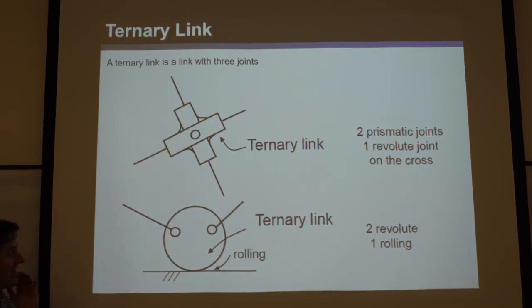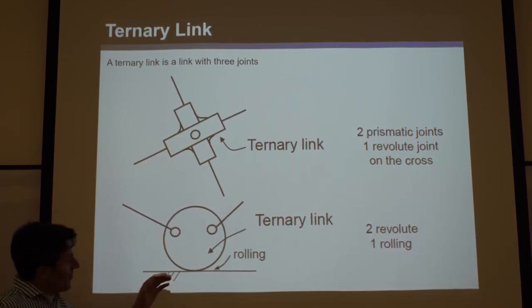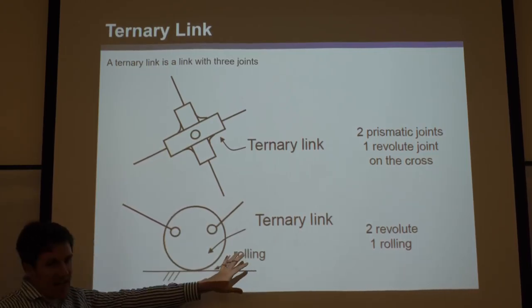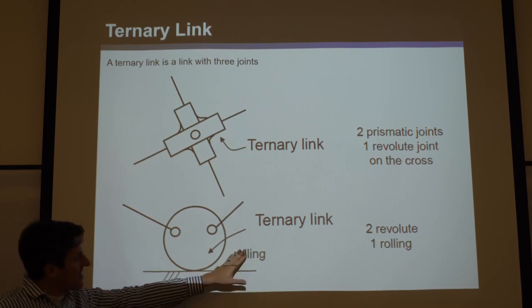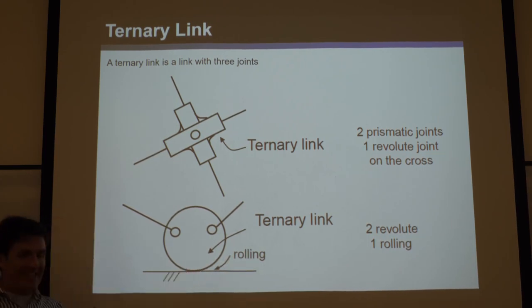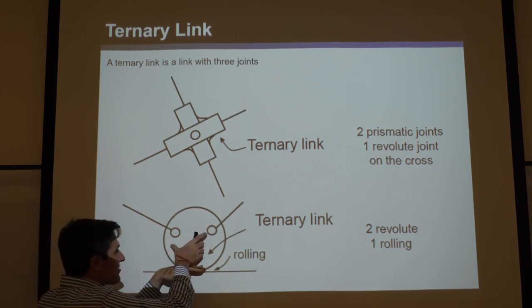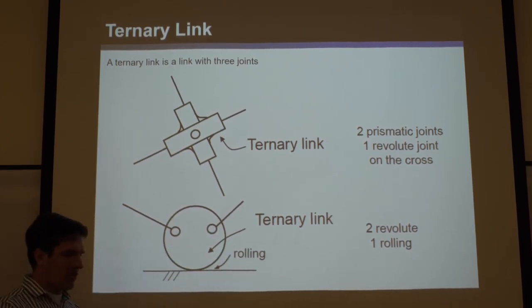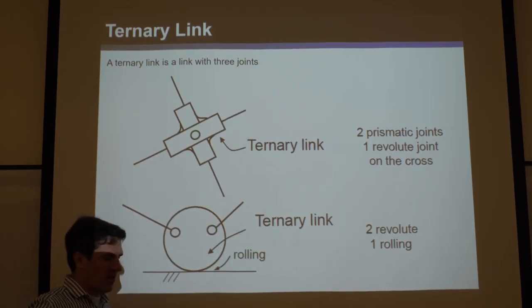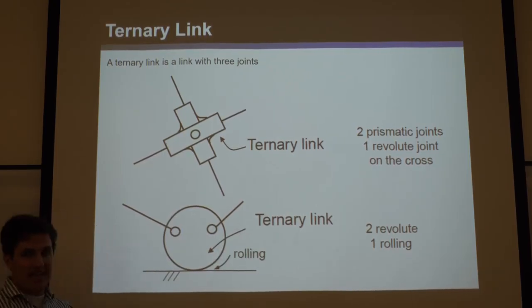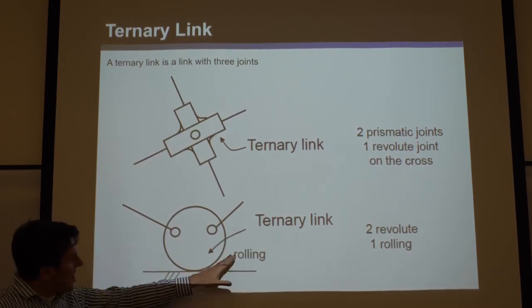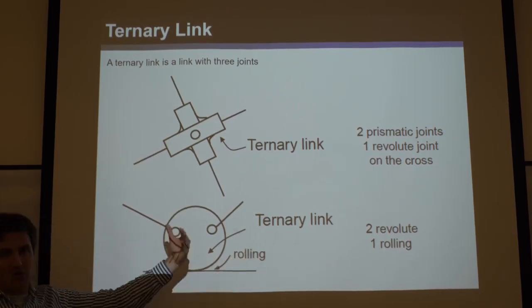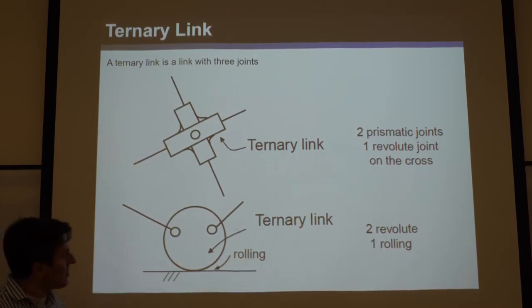So you ask yourself, first of all, whether this said rolling or not, it doesn't matter. If it didn't say rolling, then you'd assume it can roll and slide. That means you could imagine this just shearing along. Like, when you drive your car, the wheels are rolling, but when you slam on the brakes, if your car keeps moving forward, the wheels are sliding. So if this is not constrained to just roll, then it could roll and slide. So it's 2 degrees of freedom down there.